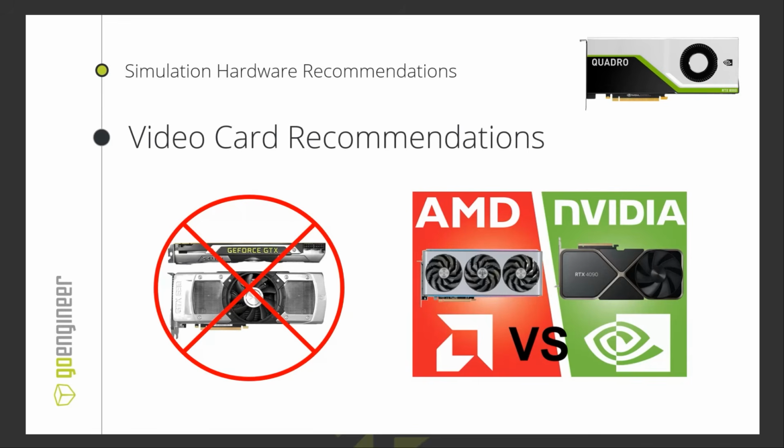Or when I used to teach SolidWorks CAD back in the day, the question would come up: video card recommendations and gamer cards versus CAD cards. An easy experiment I would do for my students: if you guys have SolidWorks open right now, start a sketch and just draw a little line segment. You'll have the line segment and two endpoints. Now zoom into one of those endpoints, and eventually you're going to start to see your endpoint on the line segment disassociate or jump away from the line segment.